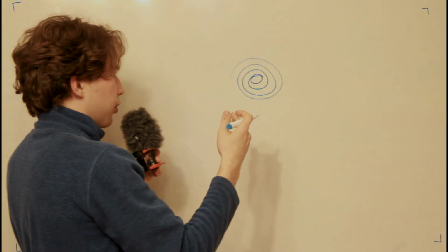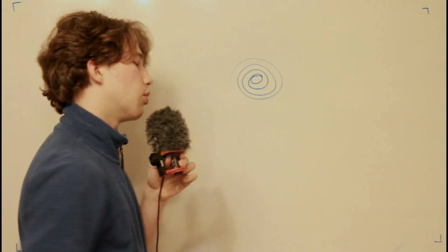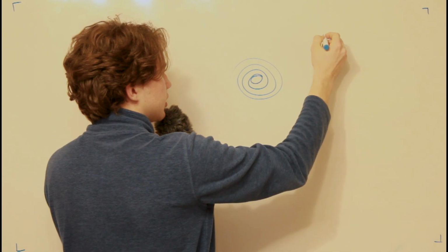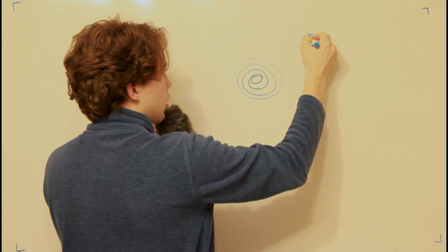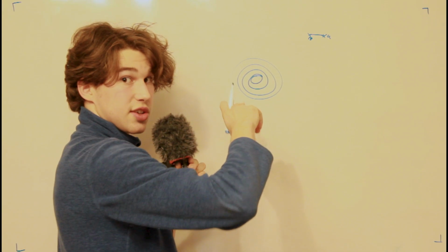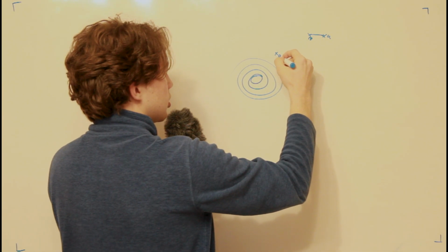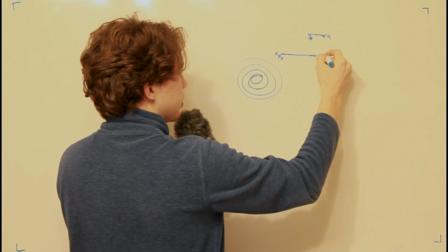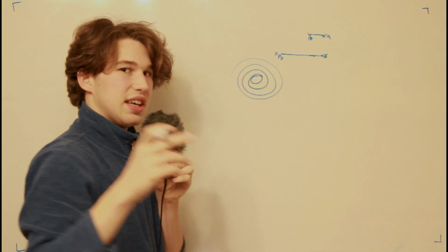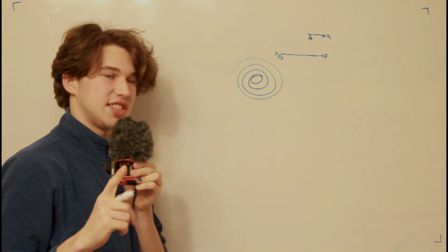So when all our cable is wound up and the distance between the anchor point A and Floaty is small, then one rotation of this motor is going to result in a bigger give or take. But if we have a big distance, say between B, then there is going to be less cable given or taken. I hope this is understandable.